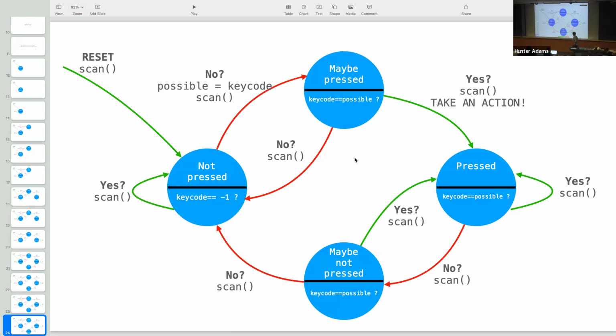Yeah. So you're making the correct observation that last time I stated that if you care a lot about timing, you don't want to use the threads to enforce this timing, because you don't know exactly when that thread's going to be returned to. So in the event that your application included another thread that was going to be hogging a lot of CPU, then yes, you'd have to come up with some other mechanism in order to get, on the order of tens of milliseconds, scanning of the keypad.